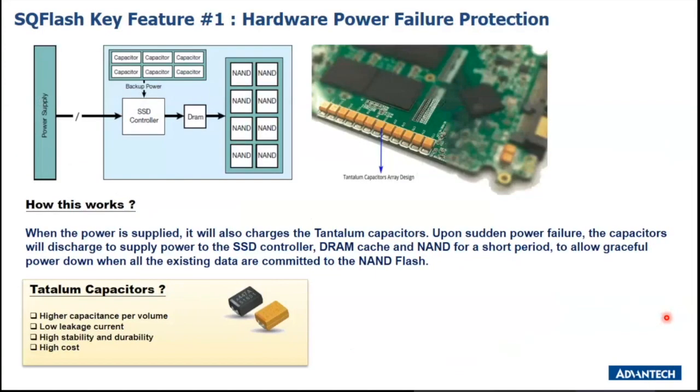All right. Besides that, we also use the tantalum capacitor, as you can see here, for hardware power failure protection. So how does it work? When the power is supplied, it will charge the tantalum capacitors behind.